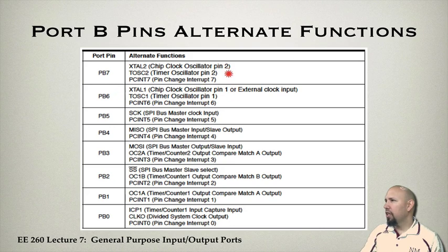So each of these port numbers has different things going on with it. I notice I can have things associated with timers, like the crystal oscillators, or these timers in terms of certain oscillator pins. I can also have pin change interrupt. Pretty much every port can have what's called a pin change interrupt. When we talk about interrupts in more detail, we'll explain what that's all about. There's also the SPI master clock on pin 5.